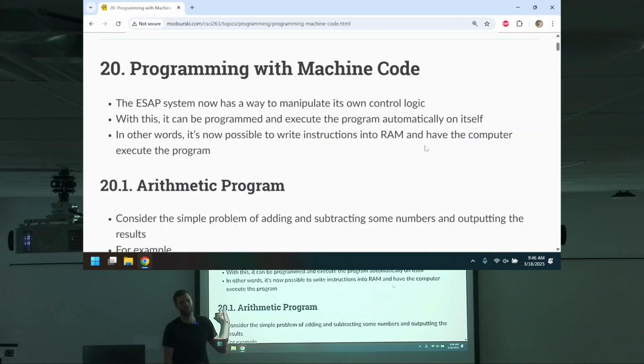Well, we output the data from a specific RAM address. Why not always from the A register? Entirely up to us. So we can write instructions that we've defined. But the point is, our system has constraints and can have certain instructions defined for the system. And then we made decisions on what those instructions were. And we have 16. Really, we only have 13 because we left 3 no-ops. Now we can write those instructions.